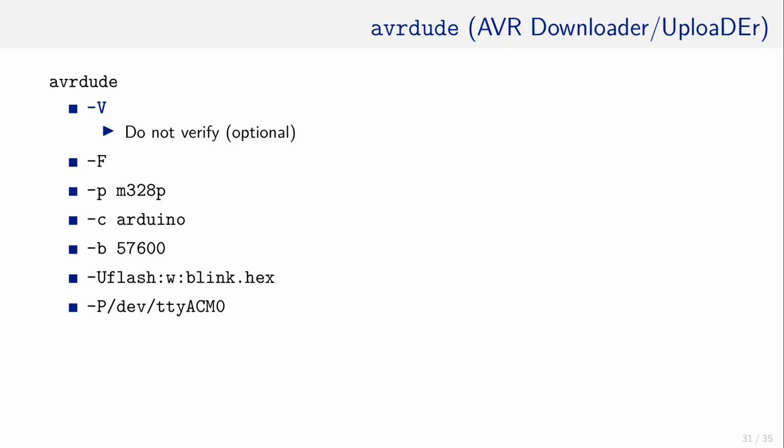Later in the course, we will remove the bootloader to be able to utilize the entire 32 kilobyte of program memory. That not only saves us 2 seconds startup time, but also 512 bytes of program memory. However, those advantages are paid for by a more uncomfortable programming method. But later more. Right now, the bootloader is doing its job.